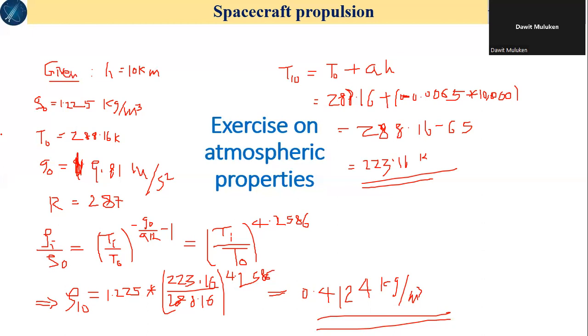Is it at 12 kilometer we are using the same formula as at 2 kilometer for finding pressure? No, from 10 to 12 I think it will be different. Yeah, it is in the isothermal layer, so the way we calculate is after calculating the pressure at 11 kilometer, then you continue to calculate the pressure at 12 kilometer, so that you can get an appropriate answer.